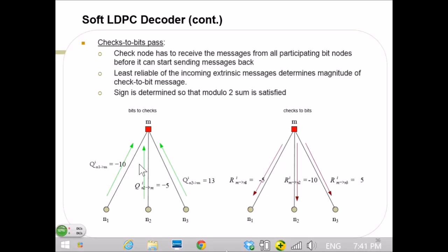Is that equivalent to doing a trellis decoding on a two-state code, essentially, but you're just optimizing? I never quite... because it's just a parity check code, which is an accumulator. And normally, when I think of that, I just soft decode it with the two-state trellis, with the BCJR.